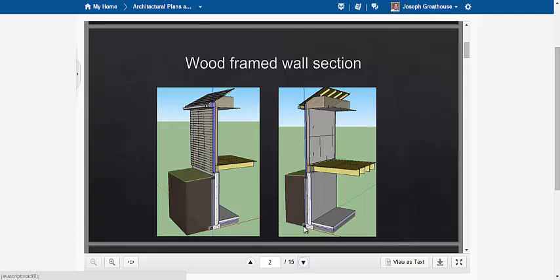On the outside, we have this weird looking little circle here. That is your drainage tile. And that tile is typically a 4-inch perforated plastic tube, basically, that goes all the way around the outside of the footing. That drains into the house.